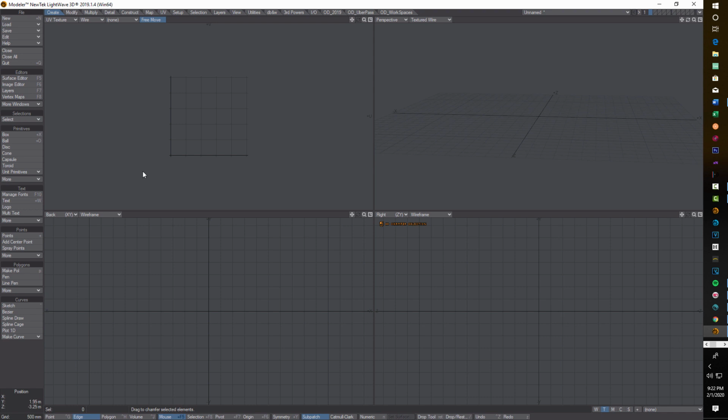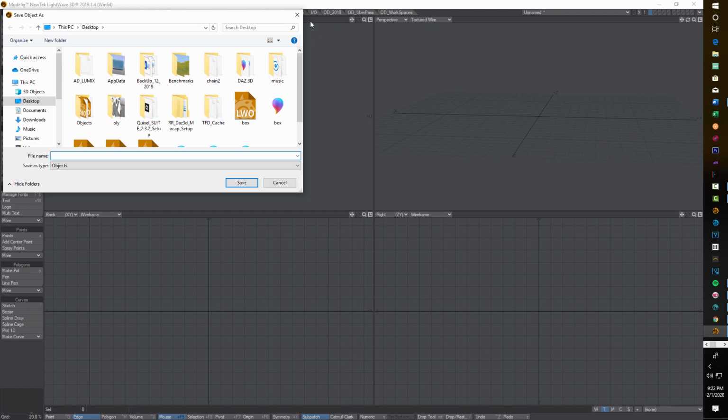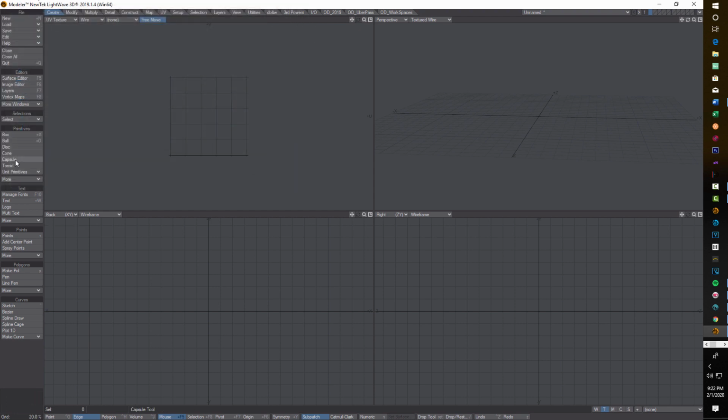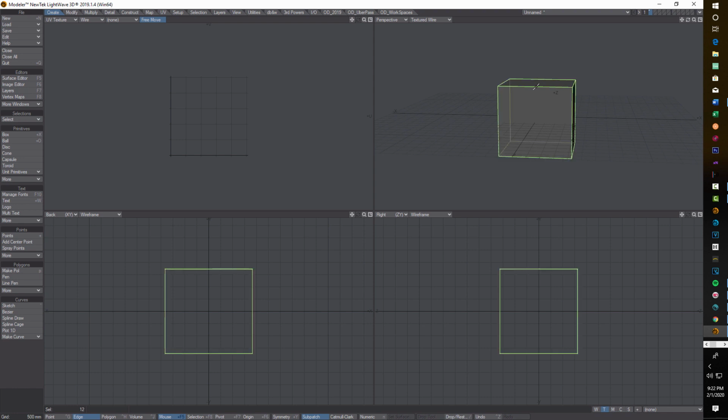First, we're in Modeler, and I'm just going to build an object here. I'm not going to load one, I'll be on Create, and I'm just going to make a box. Oops, gotta be on the box first. I'm just gonna click and hit F2 and center it. And then I'm gonna come down here to Edge, enter to drop the tool, now on the edge tool, and then the right bracket to select everything. And then I'm just gonna deselect the side points right here.